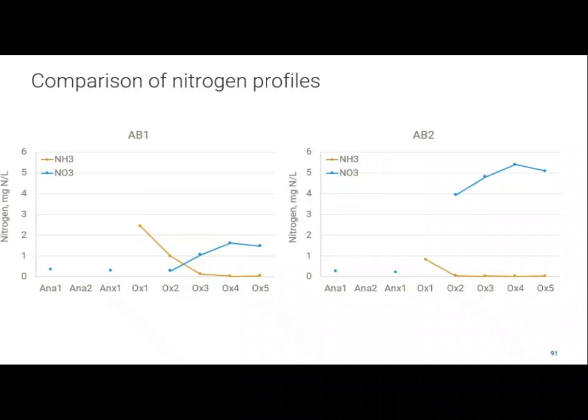Yes. But maybe you don't believe that, again, everything gets down to your limit of detection. And when you're using Hach kits, getting below a 1 on a nitrate, you're getting below their limit of accuracy, right? So if you go out and do these tests, just always be thinking about limit of detection. What am I actually measuring?